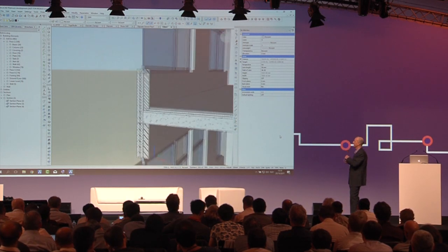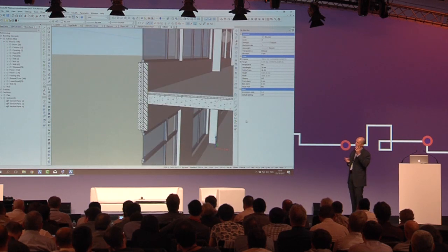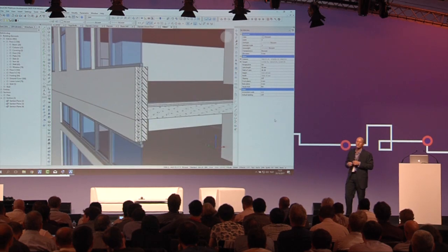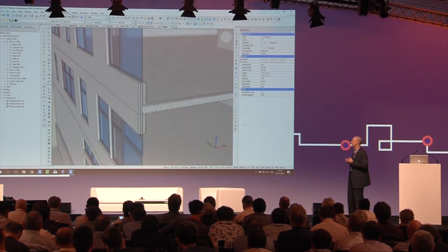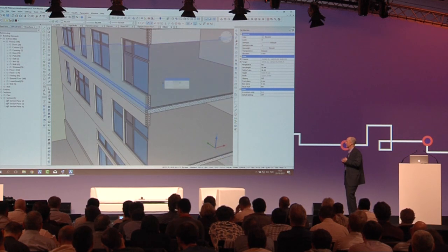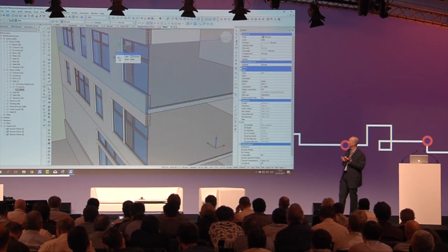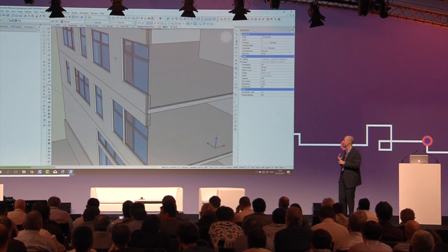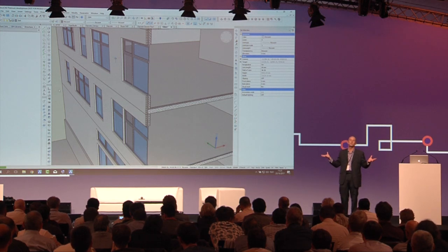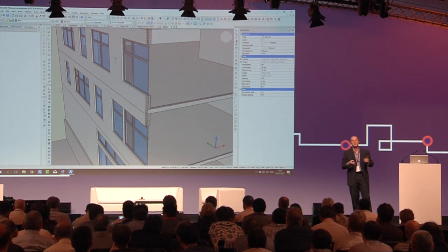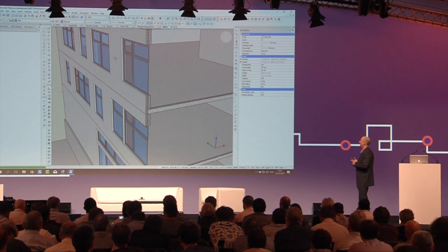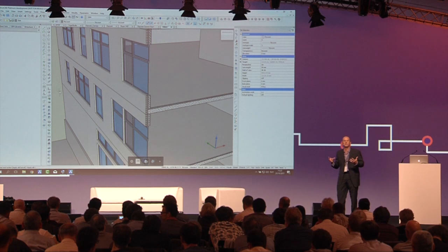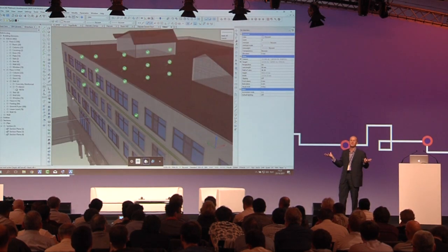Now, if we look at the floor connections above and the floor connections below, those are just the default. So it seems like an opportunity where we could use BIM Suggest. We can select the wall and then select the floor and launch BIM Suggest. What this is doing is searching the whole model for connections that are similar in terms of type and size, and then it's going to present those to us as suggestions, which is where the name comes from.